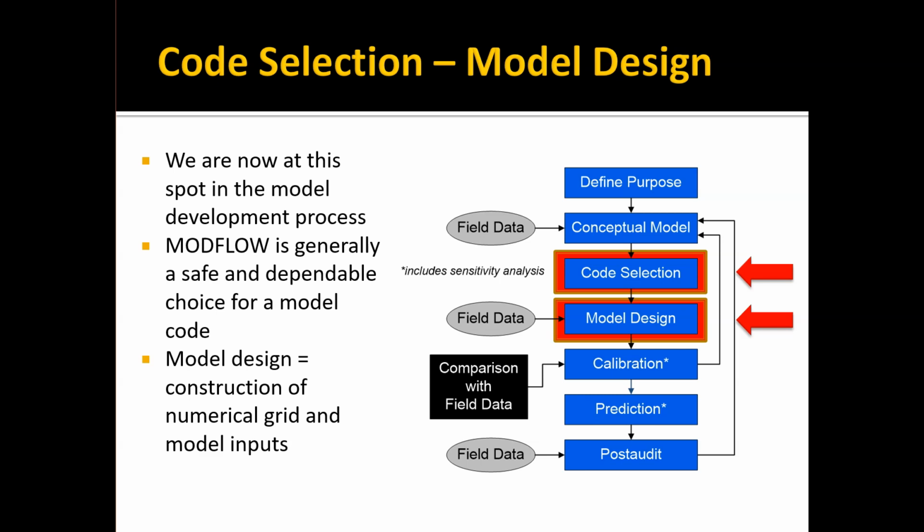And this basically amounts to preparing the input files describing the geometry and properties of our aquifer and the stresses, the sources and sinks, and then launching Modflow to run that and then viewing the results. We're going to use a graphical user interface that will really facilitate that and make it much easier, but that's what we're talking about, building the numerical model.